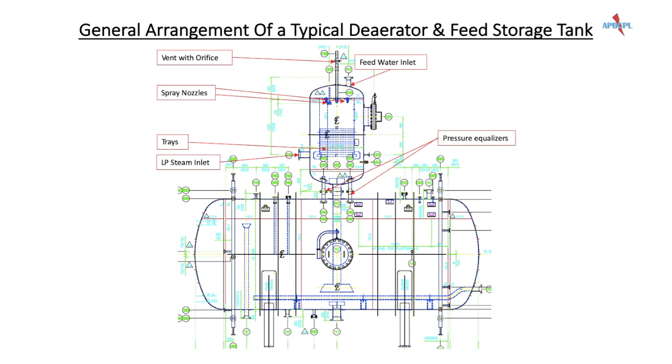Now we shall identify the parts of the feed water storage tank. There are a few auxiliary stubs provided on the feed water storage tank, namely for vacuum breaker, pressure gauge, feed pump tap-offs, HP condensate returns, startup vent, etc. The safety valve is mounted on the feed water storage tank to prevent the operating pressure exceeding the design pressure. The overflow pipe allows the excess water to be drained off safely just in case the level in the feed storage tank reaches a very high level. An automated valve is also installed in some cases and it opens when the level exceeds the preset high value.